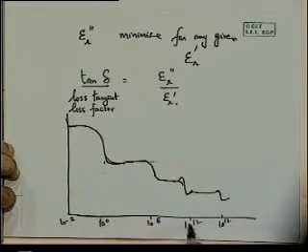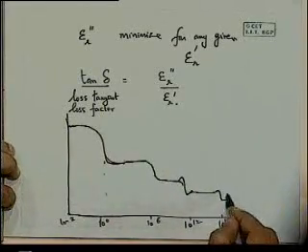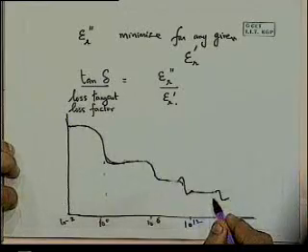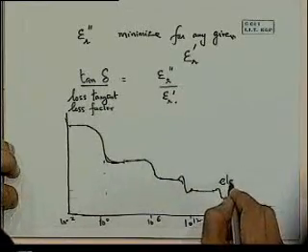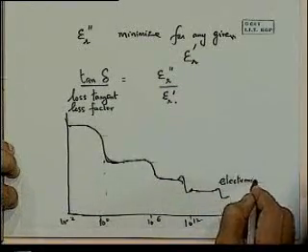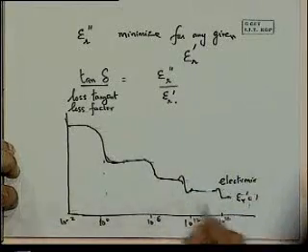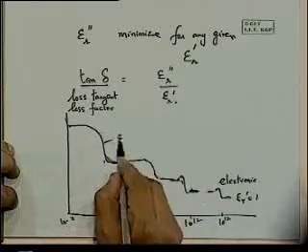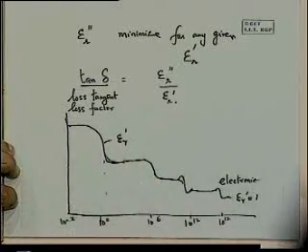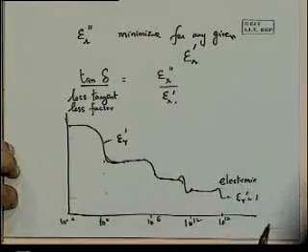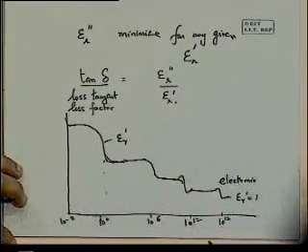You might guess from looking at this that this part is due to what? Which polarization mechanism? Which one sustains to the highest frequencies, I said? Electronic polarization. All right? Then it eventually tapers down to 1, the real part of it. Okay? So the electronic one can sustain to the highest frequencies and contributes to the polarization at high frequencies.